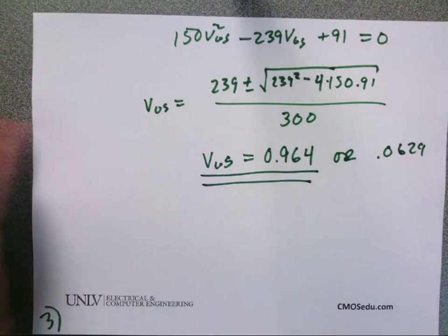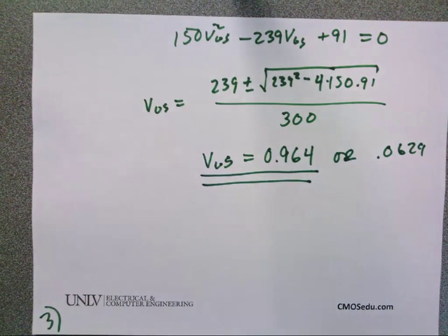Well, there's some circuits that operate at sub-threshold, like your calculators and your wristwatch, and people do bias at those voltages, but there's challenges with matching, because if you have slight variations in the threshold voltage, you can have significant variations in the current, because in the sub-threshold region, the current is exponentially dependent on VGS. It's not a square law like in the strong inversion. So we're not going to do any sub-threshold stuff here because there's practical issues with it.